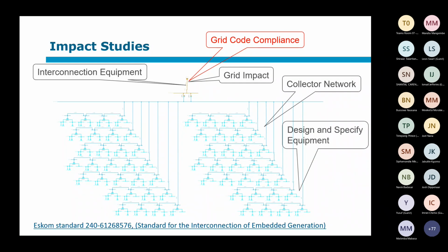And the next is that when you do the evaluation, you know how their plant should respond, because that's also contained in the grid code. So you do your studies or have the consultant do the grid impact studies for the distributor network, taking into account that you have a grid code compliant generator. And then they just have to prove that to RETEC.